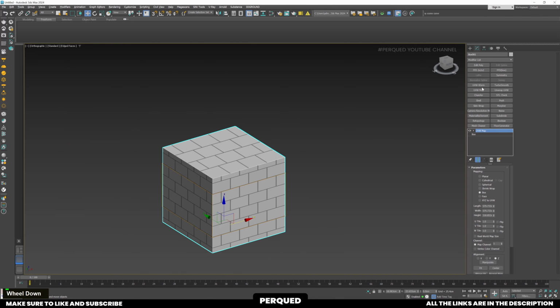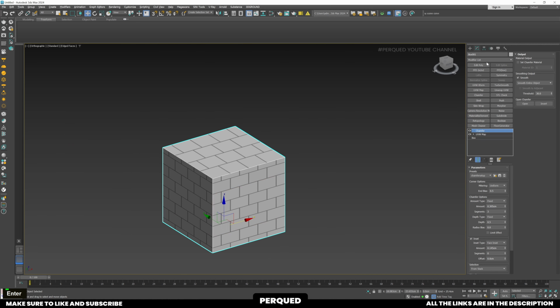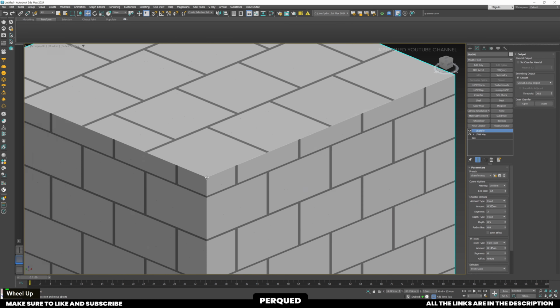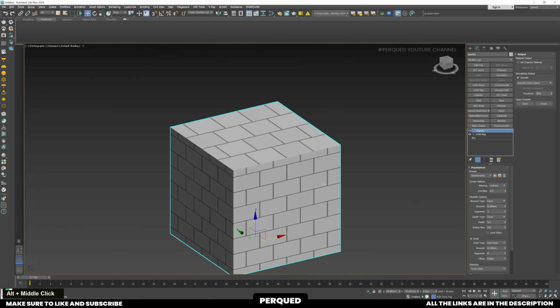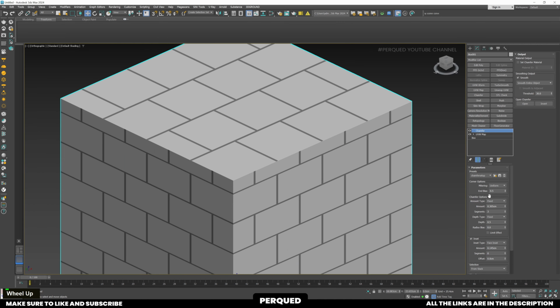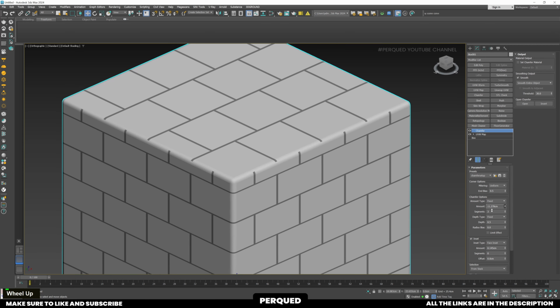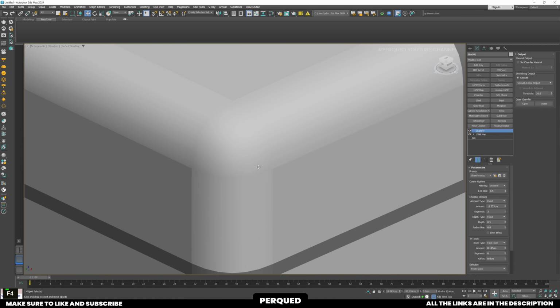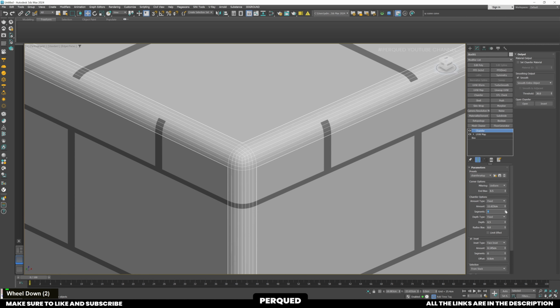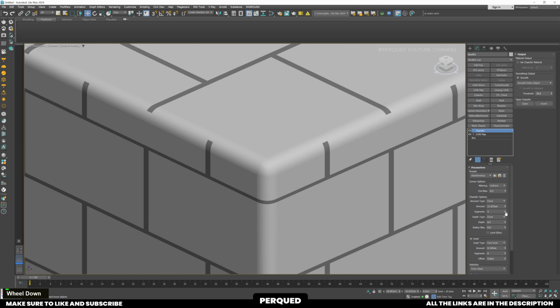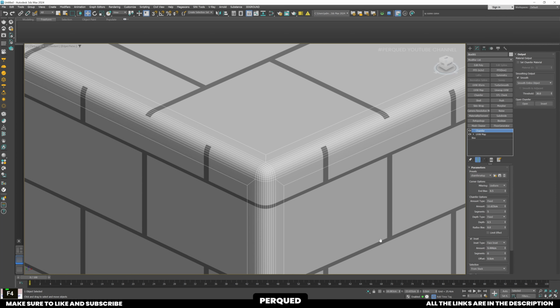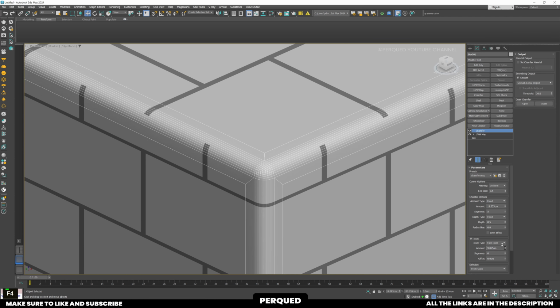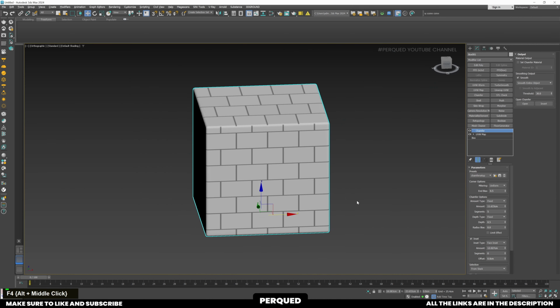Chamfer is another most useful modifier that can help smooth out corner edges. In 3ds Max 2024, this modifier is just perfect. I don't change anything extra from its settings. You have the amount of chamfer, like how much chamfer you need, and its segments. Also, we have inset. This will help you straighten up the other area after where the chamfer ends. You can also adjust its values.